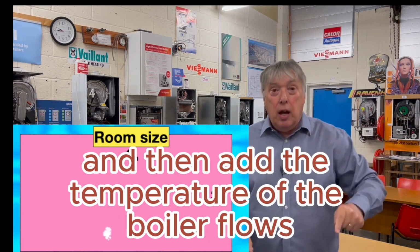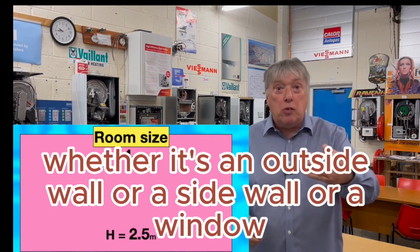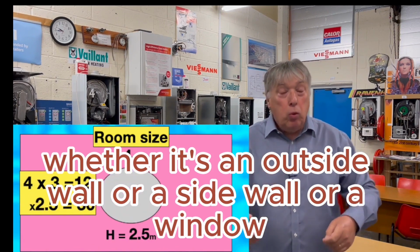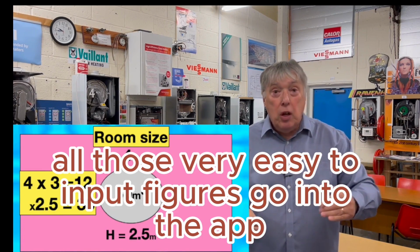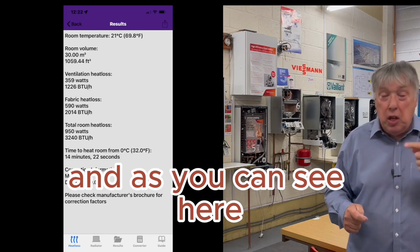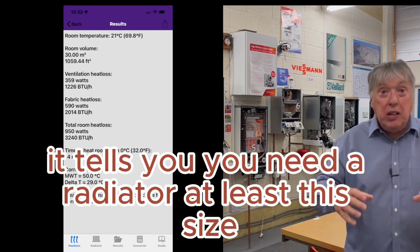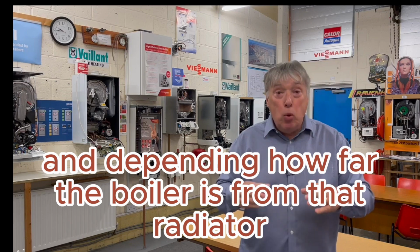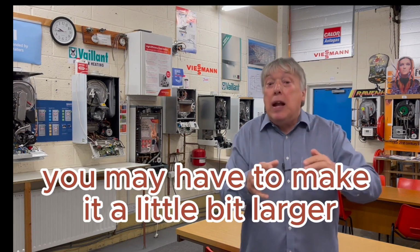Put it in and then add the temperature of the boiler flows, whether it's an outside wall or a side wall or a window. All those very easy to input figures go into the app, and as you can see here, there's the answer. It tells you you need a radiator at least this size. And depending how far the boiler is from that radiator, you may have to make it a little bit larger.